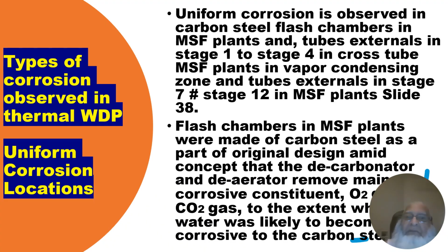Flash chambers in MSF plants were made of carbon steel as a part of the original design, amid the concept that the decarbonator and deaerator remove main corrosive constituents such as oxygen and carbon dioxide to the extent where water was likely to become non-corrosive to the carbon steel metallurgy.